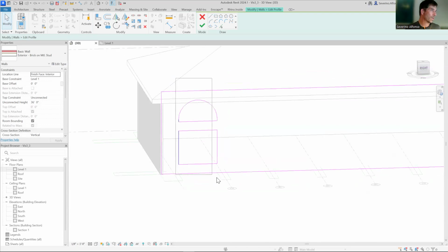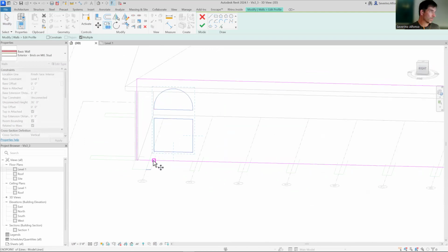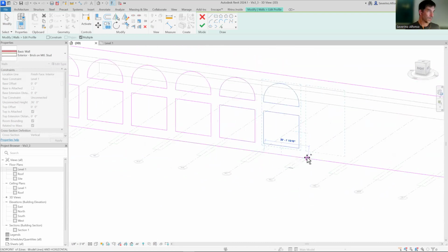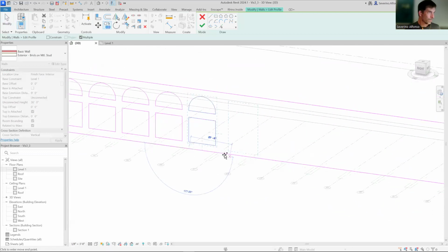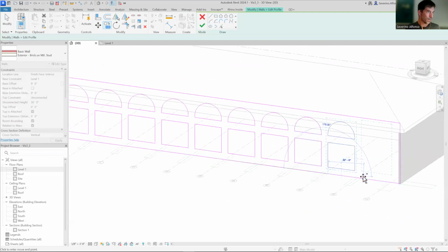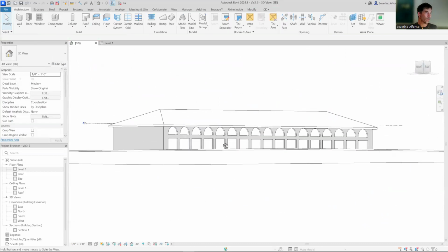Okay, so that could be our point. We can select this one and CO for copy. And you can just use reference the green lines that we did before and copy one after the other one. I don't think in this case we can do erase. And then let's just make sure that the first one works. So you have a clear set of polylines. They're closed. So you can say, okay. In here you have a number of windows.